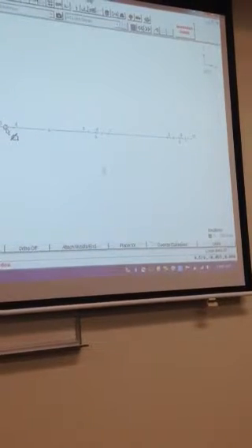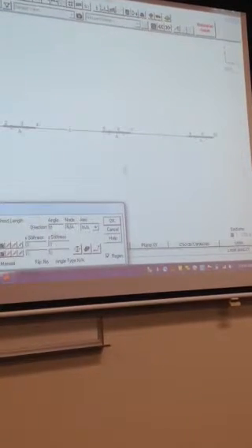But our beams are 600 deep. So this is where I'm going to use the left click and select those members. So I've got all the beams in place. Now I'll right click, properties. I'm going to change this to number 2. Alright, so number 2 hasn't been generated yet.